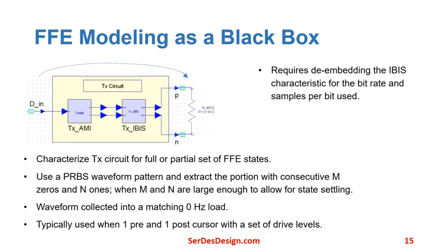This approach is typically used with one precursor and one postcursor with a defined number of drive levels. This approach requires de-embedding the IBIS circuit characteristic from each of the waveforms. This de-embedding is performed automatically during simulation for the specific symbol rate and samples per symbol used.